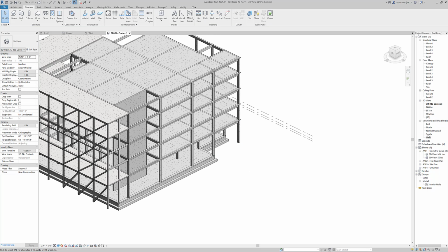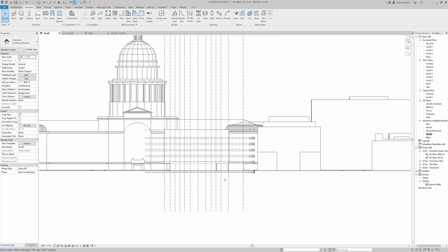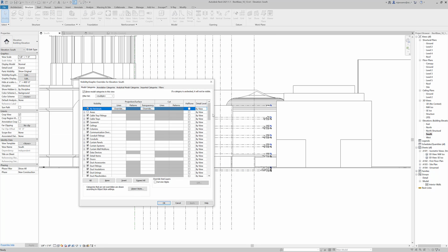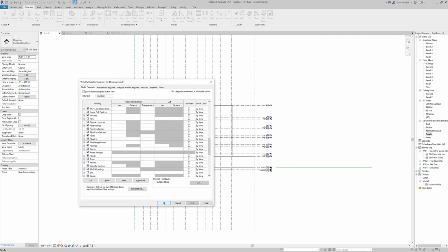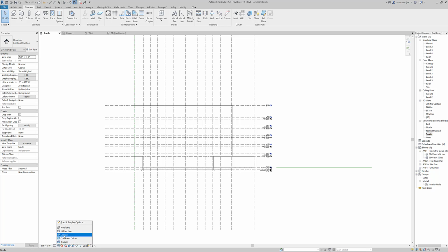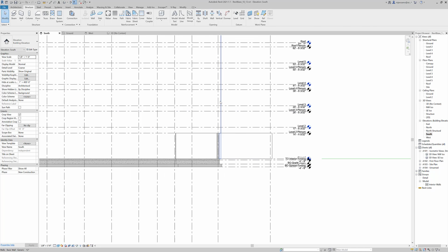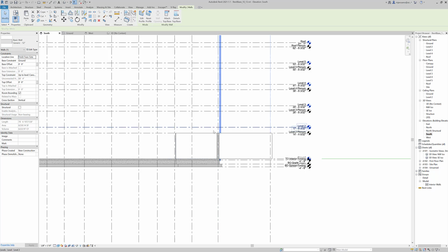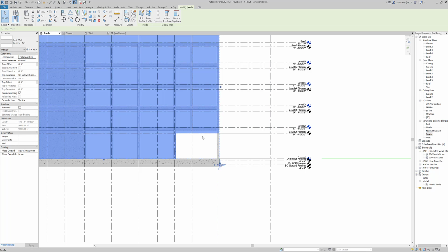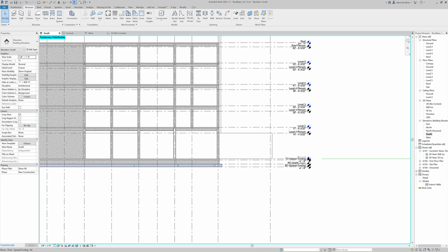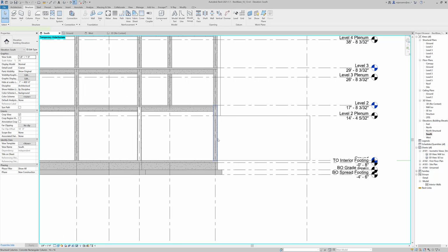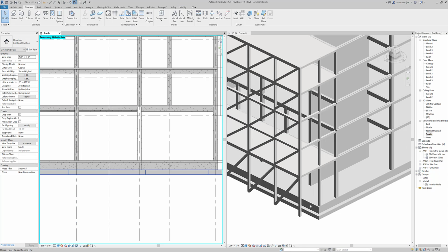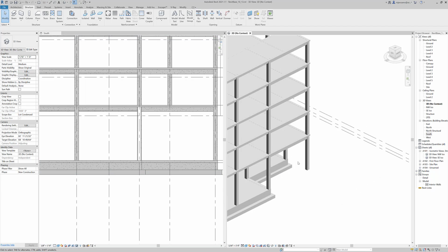I'm going to go into a south elevation, and let's just turn off the site. Yep, that's okay. And let's turn this to shaded. So here you can see I still have an architectural wall. You can go ahead and hide your wall here using HH. You can hide all of your walls if you need to, but this actually hides the structural wall here. But anyways, let me close some of these. I'll tile my windows, and you can see this column a little bit better.